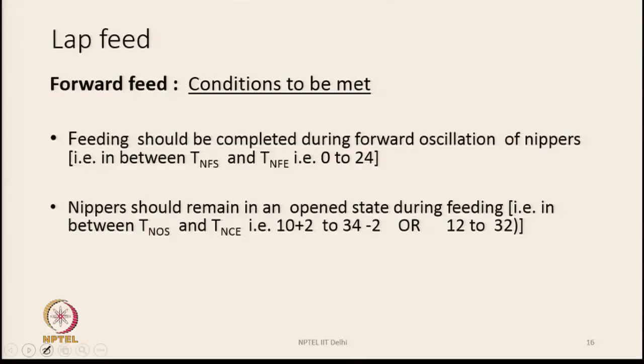Feeding should be completed during the forward oscillation of the nipper. We know the forward oscillation timing for the nippers is between 0 and 24, as you have seen earlier. So that means we have to feed the lap between 0 and 24. That is the first point.